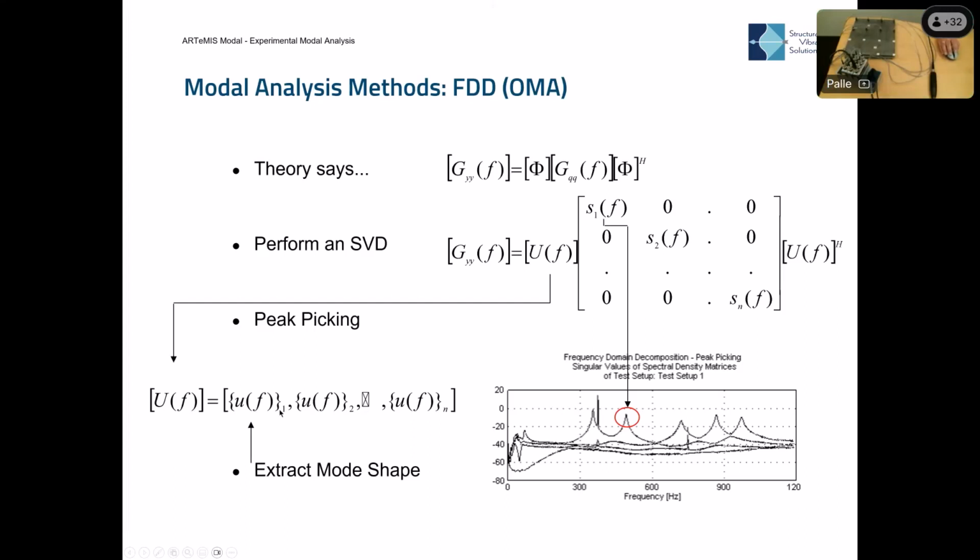And we can immediately animate it, and we can use it to estimate damping and improve the frequency estimate and so on. But the first fundamental part is simply to extract this one to get the mode shape. And this is what we do in the FDD method.